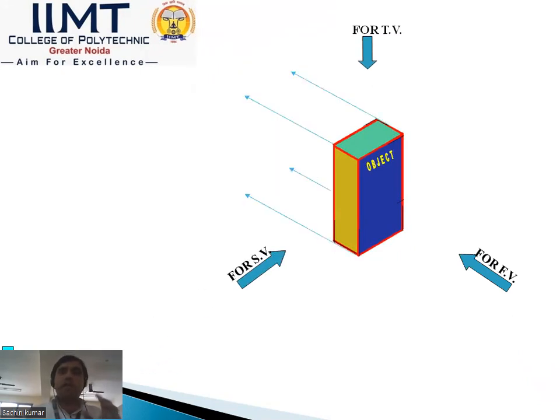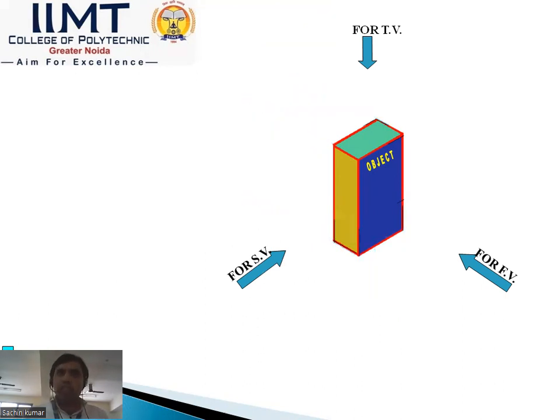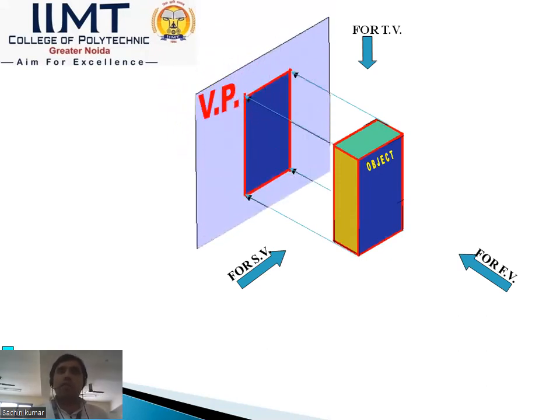The projector lines are parallel to each other and also perpendicular to the plane of projection, and this is called orthographic projection. If these lines are inclined at any angle, such as 45 degrees, that is called inclined projection.